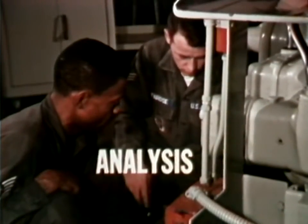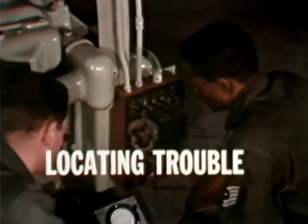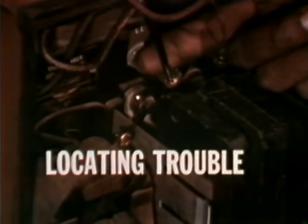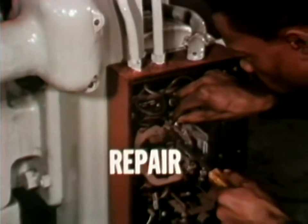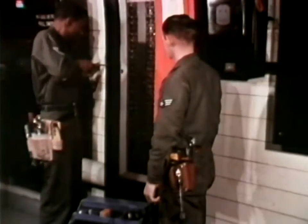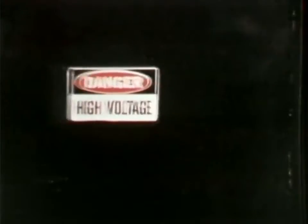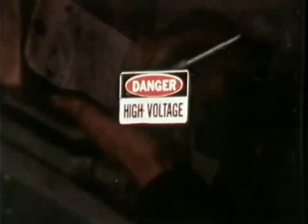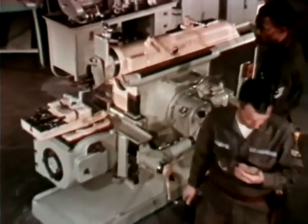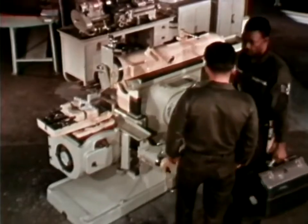Analyze the information that has been obtained. Locate the actual position of the trouble. Perform the repair. If you master this planned, logical approach to troubleshooting electric circuits, you will prevent damage to equipment, save unnecessary labor, and prevent the loss of man-hours important to the missions of the United States Air Force.